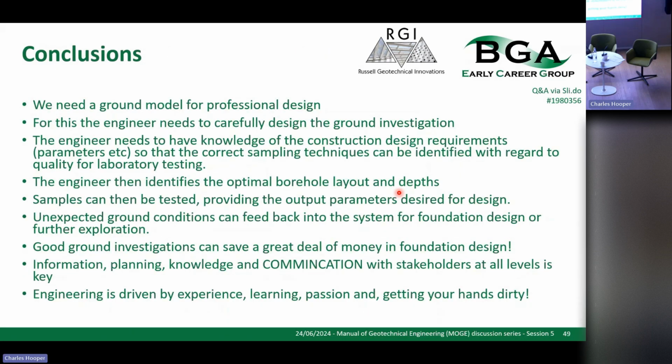Okay, in conclusion, we need a ground model for professional design, and for this the engineer needs to carefully design the ground investigation. This is the problem, because the ground investigation being designed means that you already need to know what laboratory testing you need, because you need to know the parameters that are required for the design. Now, the problem with that is if you know that, that tells you what type of drilling and sampling you need. However, that's usually decided a little bit later down the line.